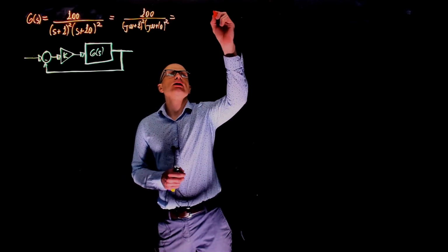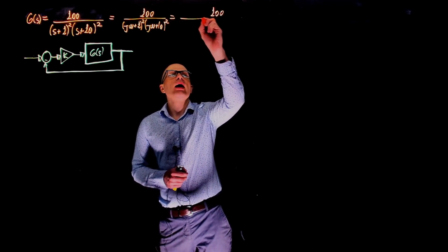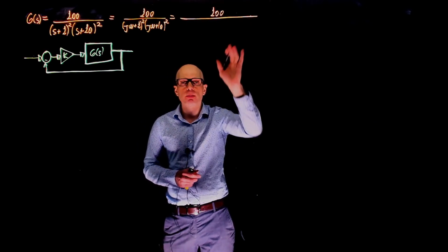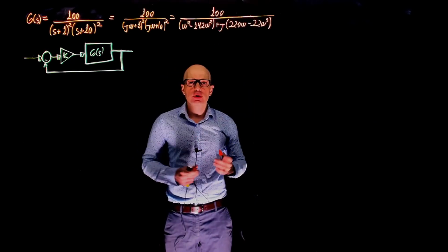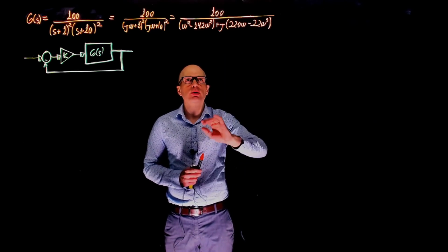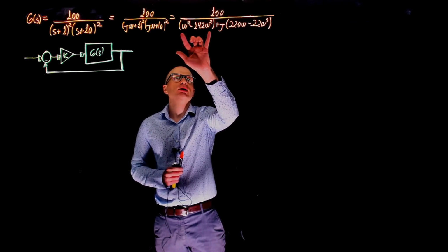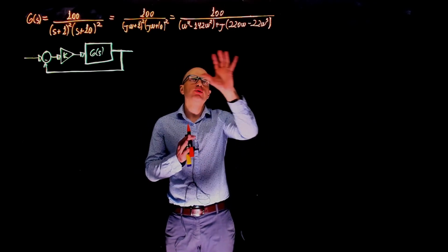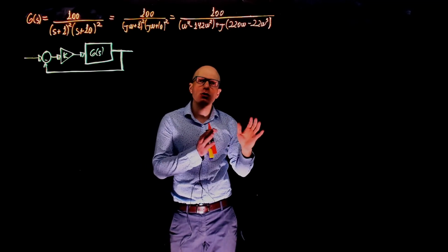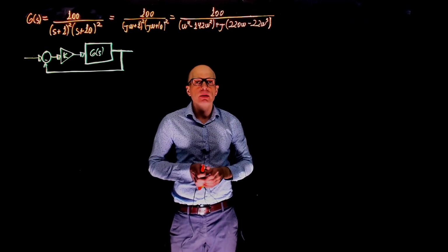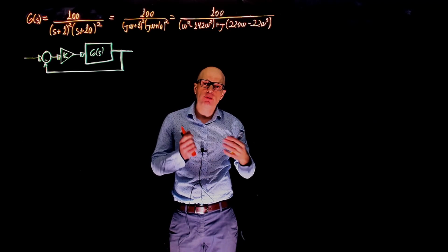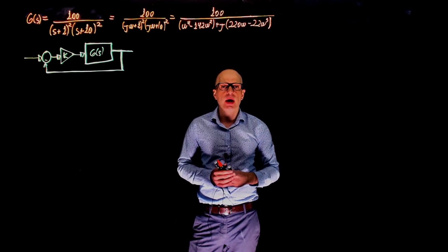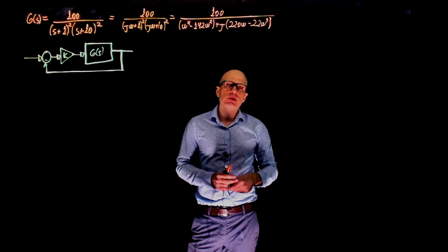And you can now expand this. This is very simple math. As we expand this function, we are also looking for the real and imaginary components of the denominator. After some straightforward manipulation, this is the result. Here we can see the real components of the denominator, and here we have the imaginary components of the denominator. The reason for splitting this way is that we are only looking for the imaginary part of the transfer function, because we know that when the phase is -180 degrees, the Nyquist plot is crossing the negative real axis, and the imaginary part of the transfer function is 0.